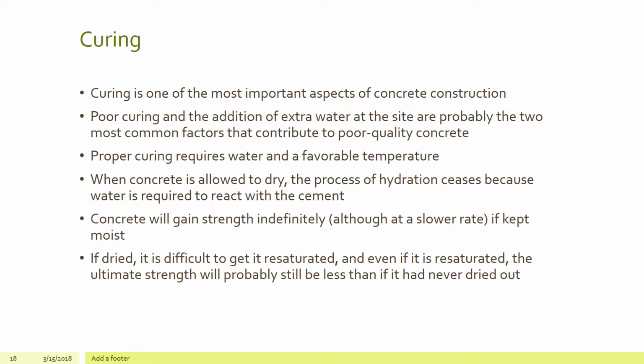Curing. Curing is one of the most important aspects of the concrete construction business. Poor curing and the addition of extra water at the site are probably the two most common factors that contribute to poor quality concrete. Proper curing requires water and a favorable temperature.